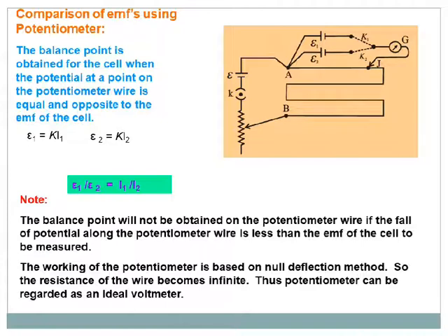The main conditions are that we are going to use the null deflection method, the battery EMF E should be larger, and the main key K should be closed throughout, and then we keep the keys K1 and K2 closed and open alternately. In this manner, we are going to do the experiment.